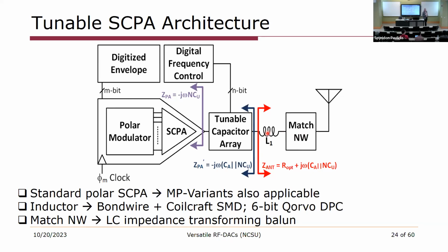Yes. You fixed the inductor, but you said you wanted it to work over really wide frequency, but you just showed us there's some optimum inductor. Yeah, there's a bit of a trade. Really, all we're doing is showing you that we want to operate with some optimum quality factor, so that's going to dictate the relative size of the inductor. We don't get everything for free, so if we could program the inductor also, it'd be a bit more optimal, but we don't have programmable inductors. But I'm going to show you nearly 60% fractional bandwidth for a digital power amplifier in just a moment.